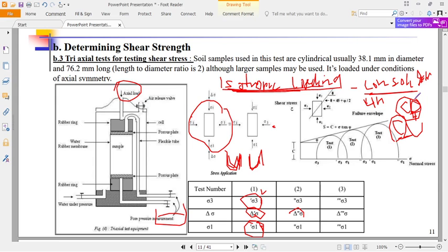We get this other curve. Under this curve, normally we know one curve is enough. We draw a horizontal line as a tangent to this curve up here. Okay? A horizontal line here. So normally, the only things you're determining here are the cohesion and the undrained shear. Okay? So here we get what is called the undrained shear. Is that okay? Which is this one here? And the cohesion will be the undrained shear, which will be the cohesion of that material.